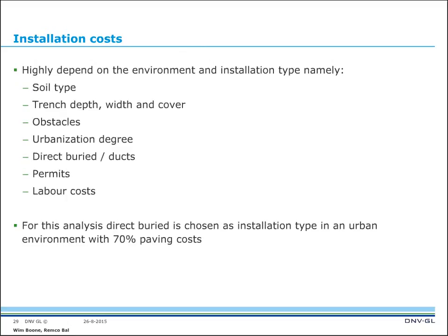So now I'll go through all the costs involved. Of course, it highly depends on several choices, but also for installation, for instance, we focused on the Netherlands. Some important parameters are soil type, trench depth, width, and cover. And if there are many obstacles, the urbanization degree is important. Also whether it's direct buried or laid in ducts.